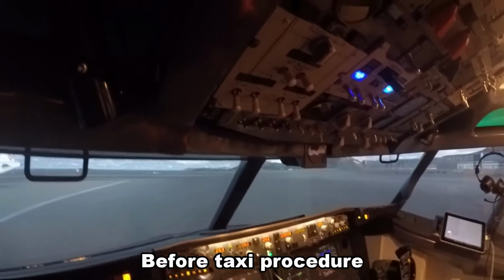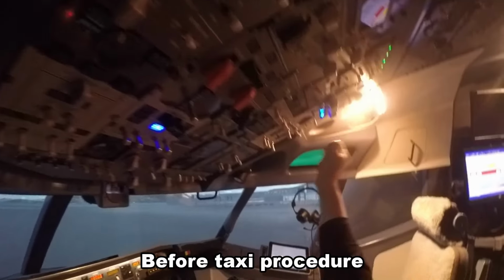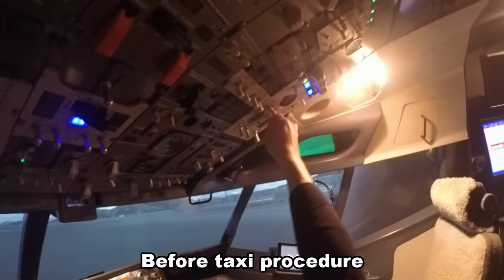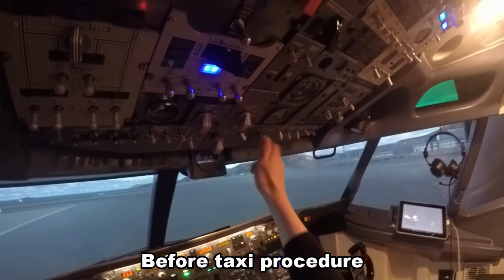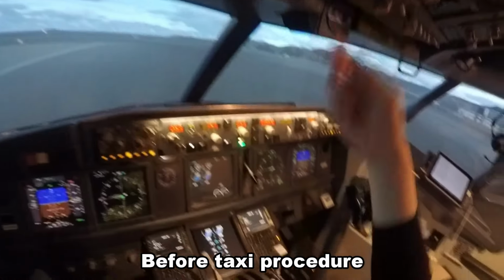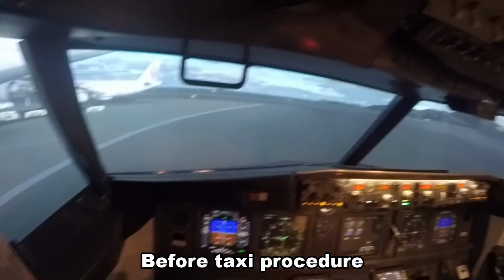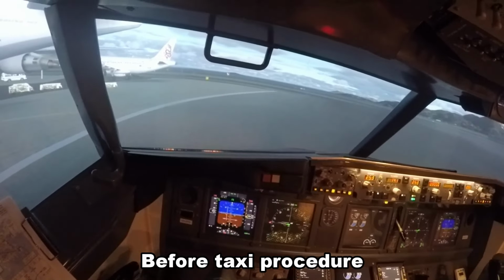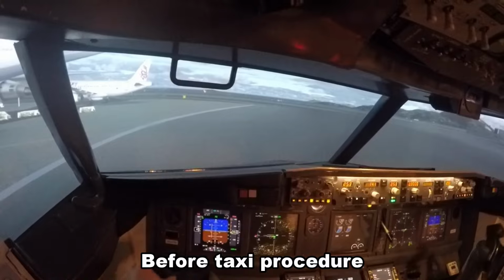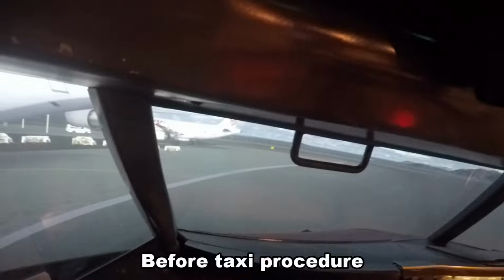Alright, so before taxi procedure, generators going on, probe on, pack sets auto, isolation valve is auto, APU bleeds are off, engine start switches to continuous, APU is going off, flaps 5, flight controls are checked, recalls checked, we're clear on the left and we're clear on the right.